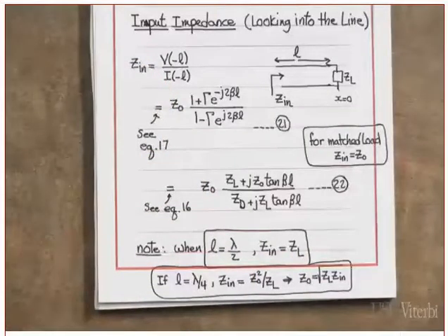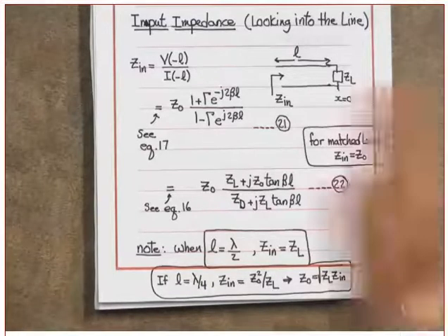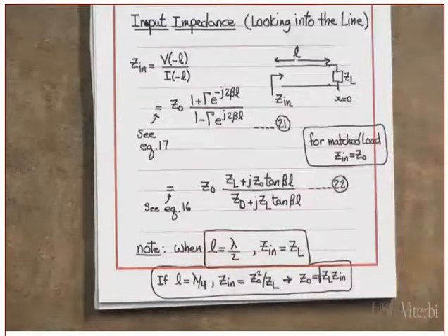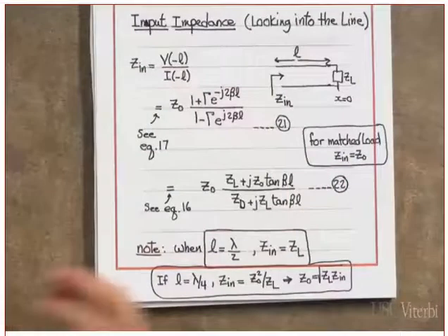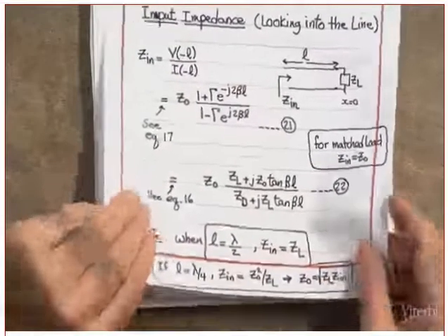So if you do have a transmission line with a length of half wavelength, it means as if it is what? As if it is not there. You can what? You can remove it. Do you follow me or not? And you put the load directly to the source. Clear? No response.